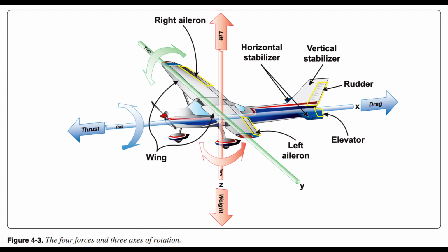Interference drag. Interference drag is generated by the collision of airstreams creating eddy currents, turbulence, or restrictions to smooth flow. For instance, the airflow around a fuselage and around the wing meet at some point, usually near the wing's root. These airflows interfere with each other, causing a greater drag than the individual values. This is often the case when external items are placed on an aircraft. That is, the drag of each item individually, added to that of the aircraft, is less than that of the two items when allowed to interfere with one another. End of page 4-3.